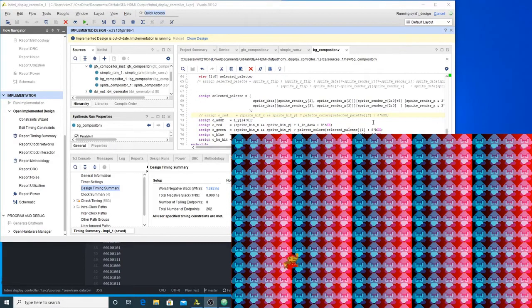left to right on the image will be the same color, but as you go down the side, you'll see that the colors will go from blue to red, and then they will overflow past color 255 and go right back down to 0. And so we'll see a few steps of blue to red, then blue to red, then blue to red in that kind of gradient like we have right now, just in the opposite direction. So we're running our synthesis right now, just to show how that's going to look when we change this to be based on the Y coordinate instead of X.